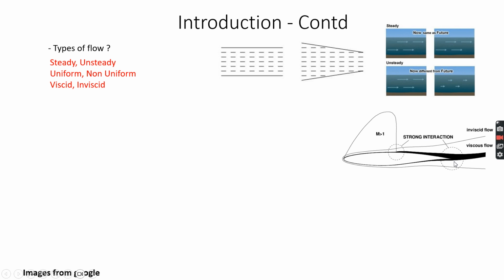So this is one challenging part for the CFD community, to get the equations of the flow for these inviscid and viscid regions, where it's difficult to interpret their behavior because the boundary conditions change over here, and also the nature of the equations, such as hyperbolic, elliptic or parabolic, changes over here because of the action of viscosity.